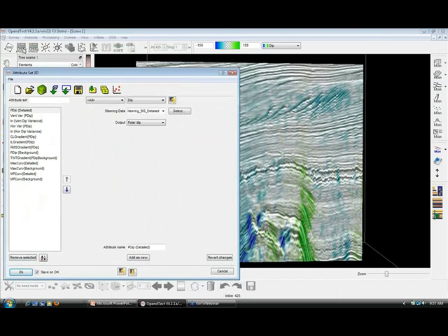The attribute engine can be accessed via the attribute 3D icon. The first thing I'm doing there is extracting, in this case, the polar dip for my detailed steering, and later we'll do it one more time for the background steering. Then you use the dip attribute, you select the right steering data, and as output you can choose the polar dip, but you can conceivably also choose azimuth.